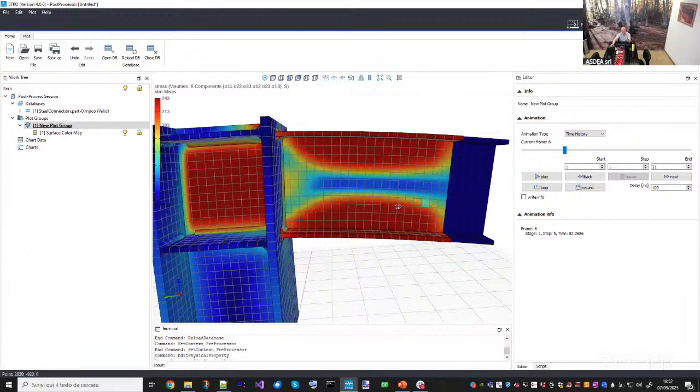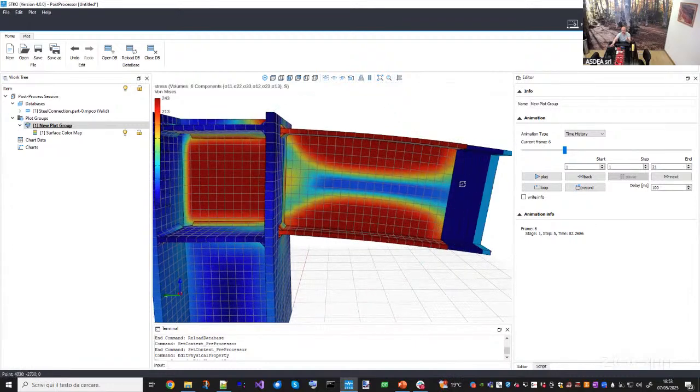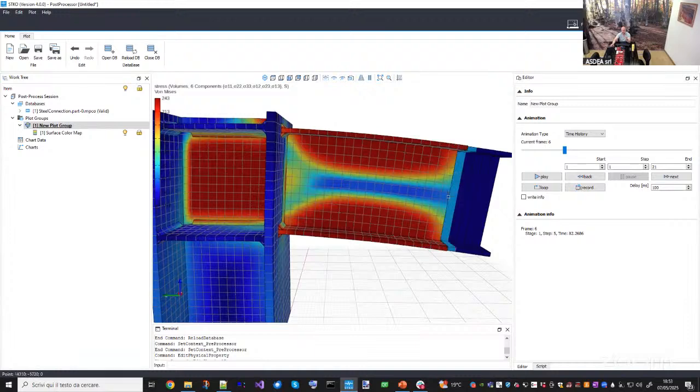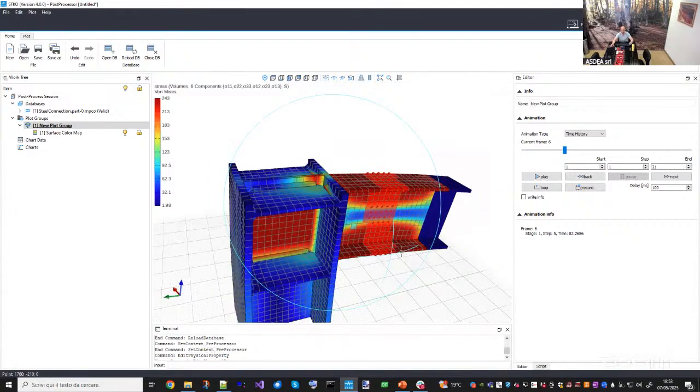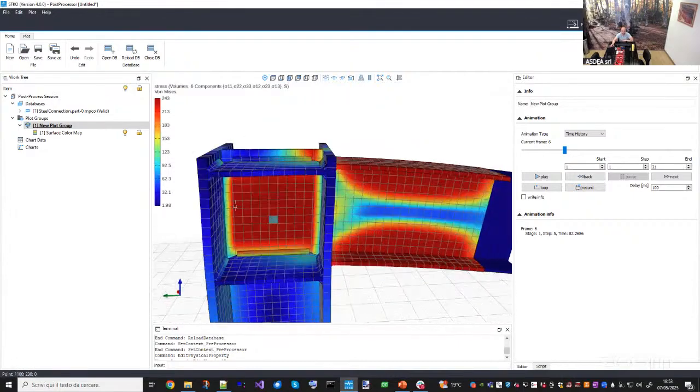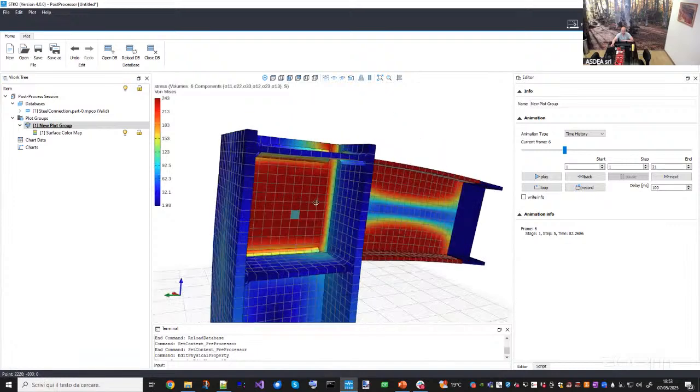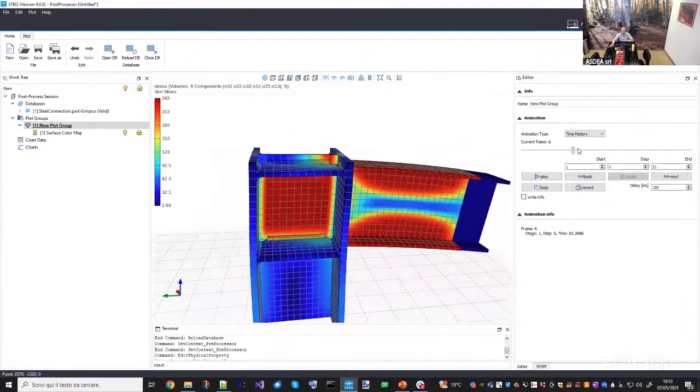Here you have a slight change in the stress distribution simply because now I'm forcing this face to be flat, which is the beam assumption. But here in the middle, you will see the typical response that you expect. And also you have a lot of plastification here due to shear, okay?